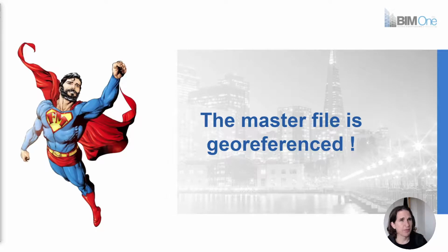Just a quick note, if your project is a campus or a site with several buildings, the master file will be geo-referenced from a site file to allow simpler modification without having to move the grid lines in the master file.